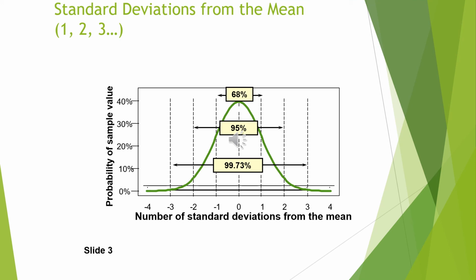So the standard deviation, as explained in the video, turns out that 68% of everything we measure will be within plus or minus 1 standard deviation. 2 standard deviations will have 95% of whatever it is we're measuring, and 3 standard deviations, 99.73%, darn near all of them. So what we're going to do is use this and see if something varies outside the normal. You can figure out probability, things like that. And that's what statistical process control does.